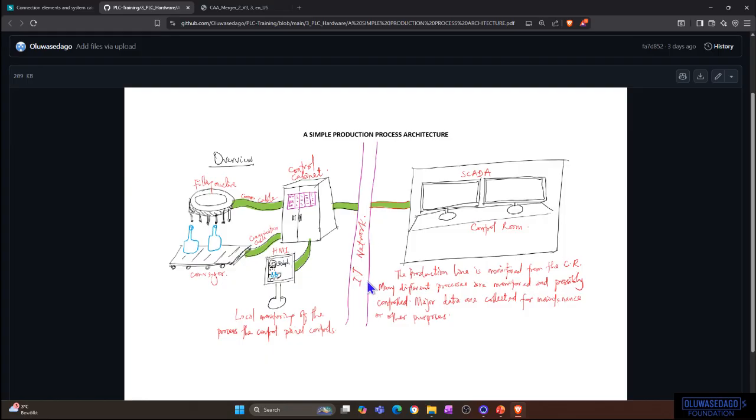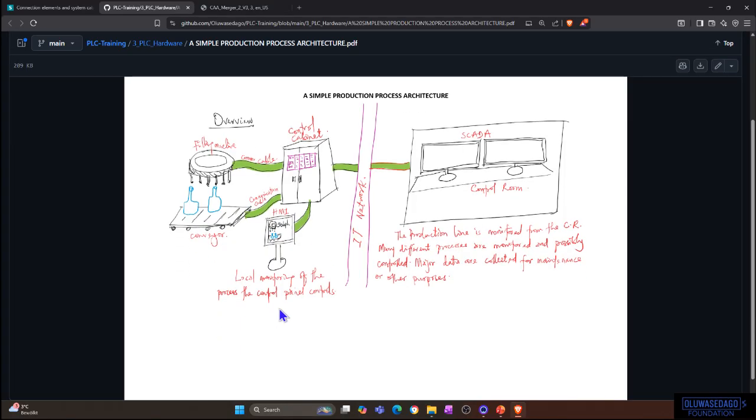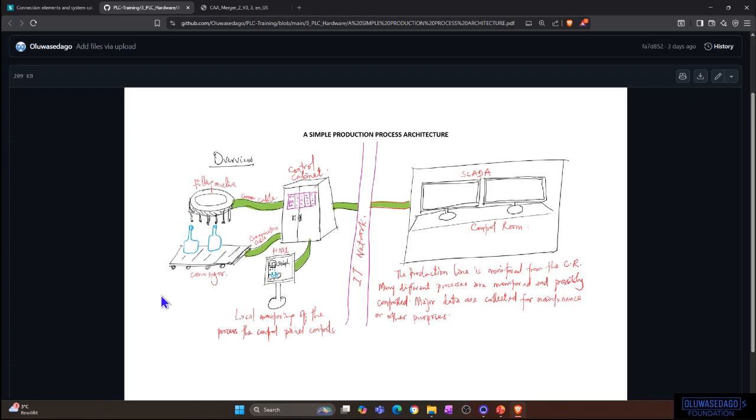In this case, you want to implement some safety, and you want to make some delineations between who can control what. For example, in many cases, the person in front of the HMI has more control than whoever is sitting in the SCADA room, because the person with the HMI can physically see the process, can easily start and stop it, and can see the effect of whatever control or information is being given to the system.